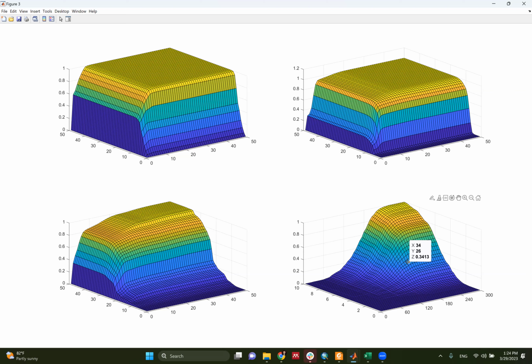Is that raw damage states or fitted damage states? We are still at raw damage states. We didn't do anything. Can you see how these fragilities look? It's not fitted. But the thing is, damage state 4 has the structural components, and the structural components are highly variable in the duration. So right now you can see the contribution from both. But for this one, most of them are electronics, appliances, furniture, so the contribution of the duration is not that high.